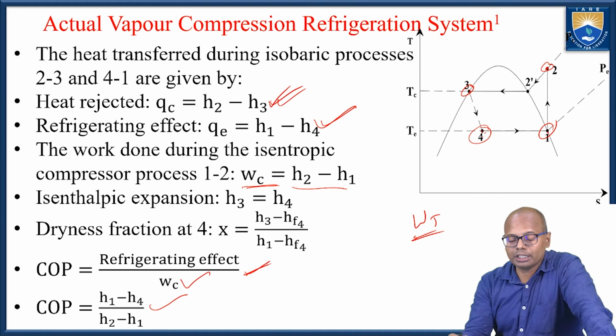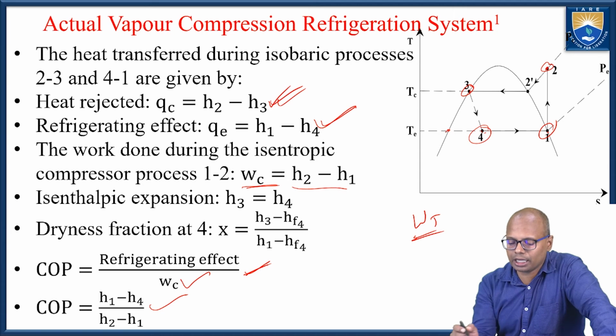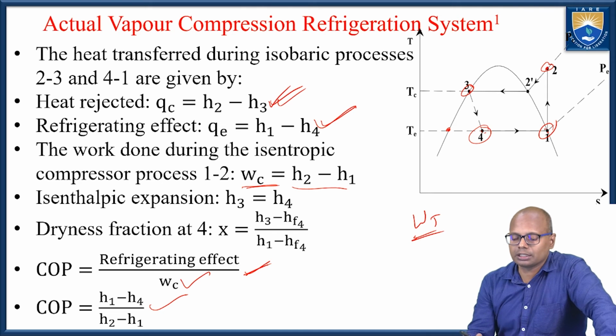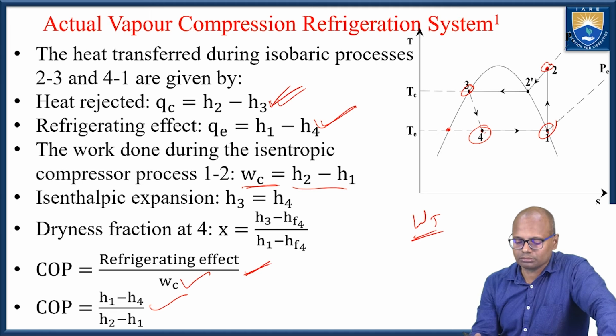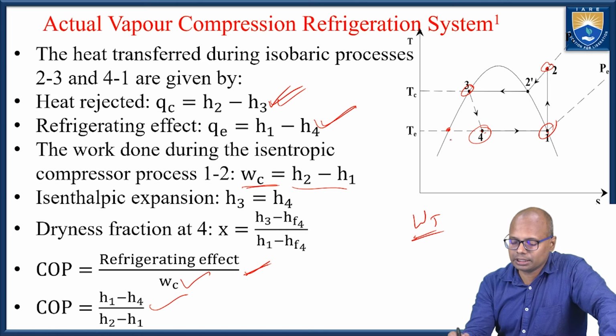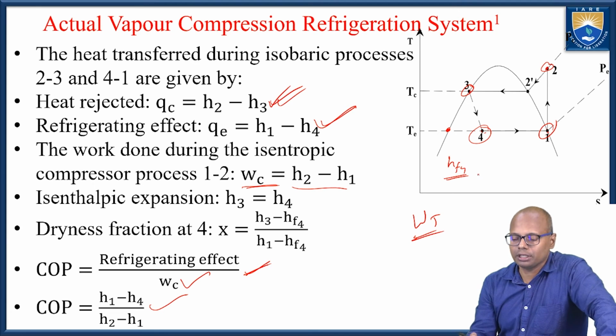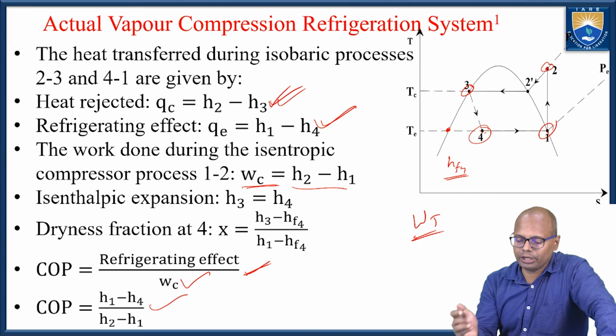Now what is H4? Here I have a saturation point. This is saturated liquid and this is saturated vapor. At this point the enthalpy is nothing but HF4, the enthalpy of the saturated liquid at this temperature.